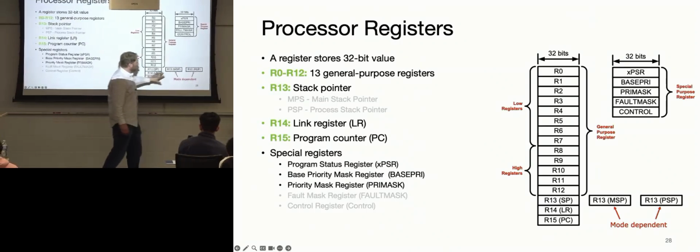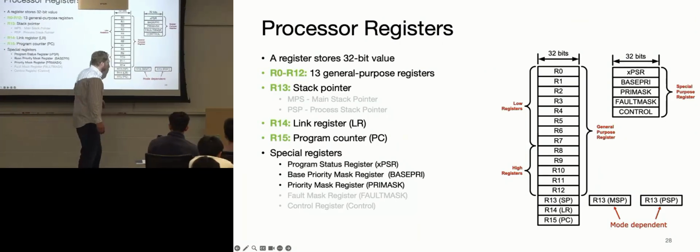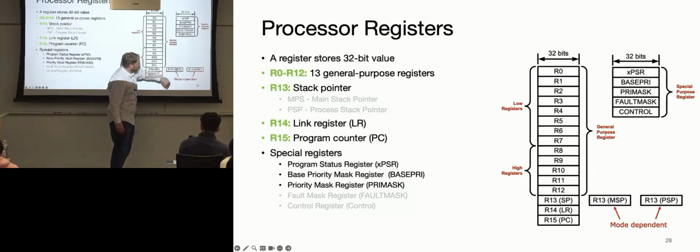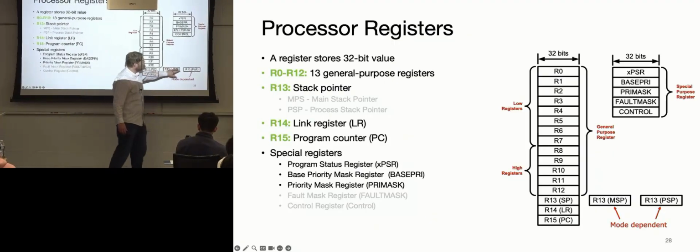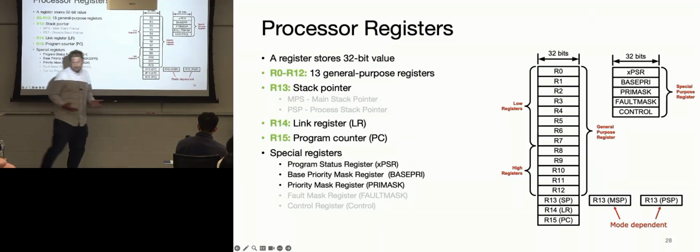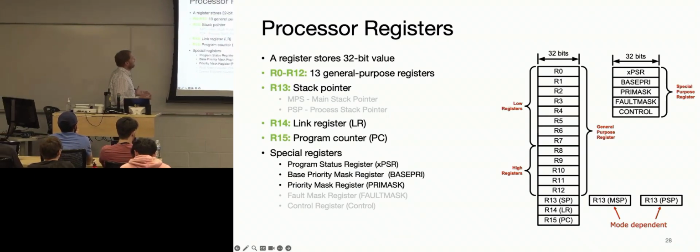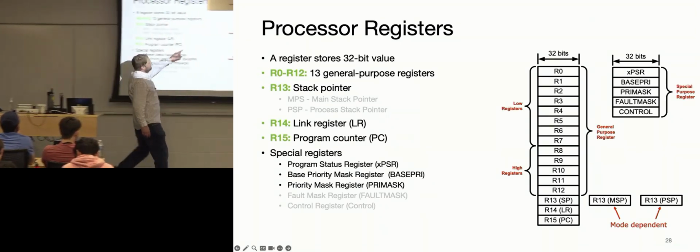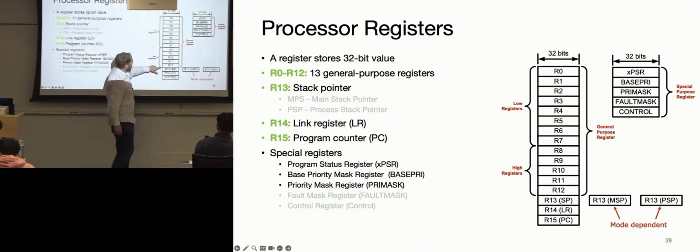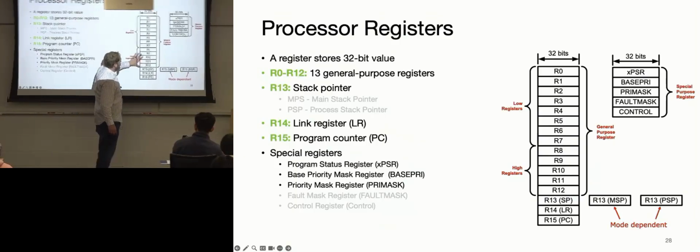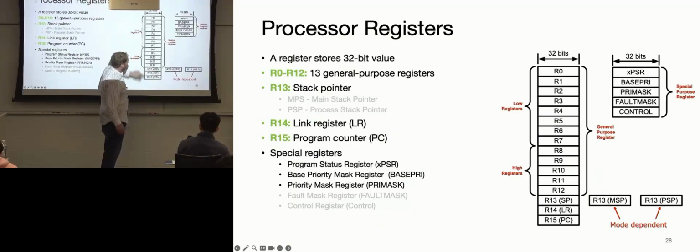There are 2 different modes your processor could be in. We don't really address that. It only comes up with interrupts. There are shadow registers that you may see, but those are privileged and non-privileged mode. It's not that big a deal right now. So anyways, you have 13 registers that can be used as scratch space, plus the stack pointer, link register, and program counter.